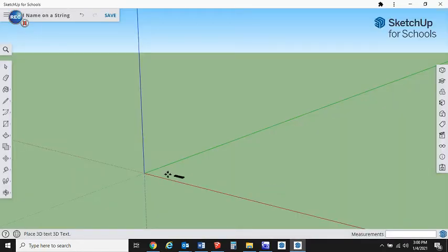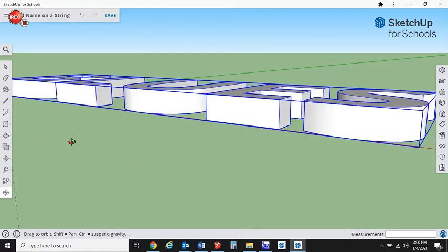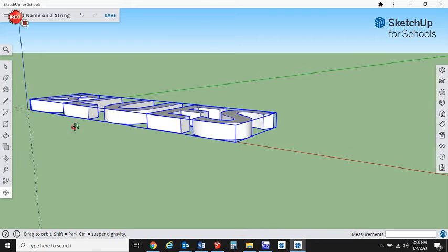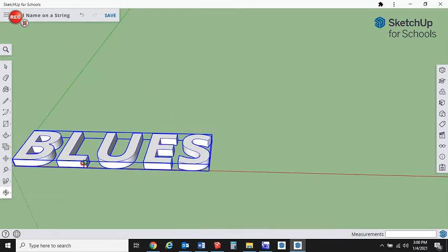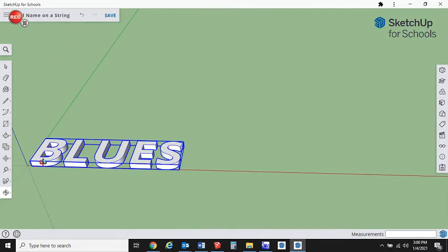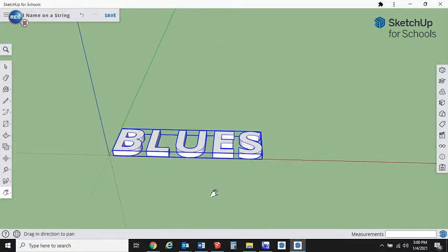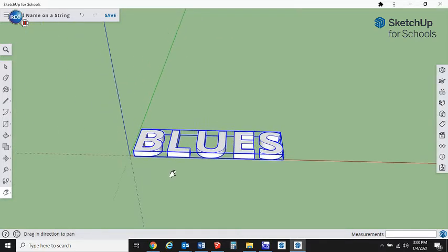We'll say there. We're going to see how it's glued to my move cursor. I'm just going to paste it at the origin, generally the easiest place to find things. And then I'm going to go to zoom extent so we can actually see what we're working on. Zoom out a little, and orbit around, and H is your shortcut for panning.